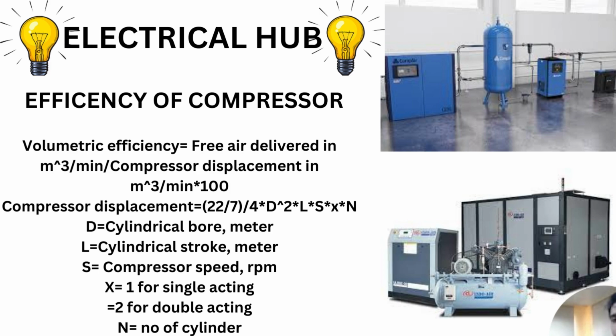Volumetric efficiency is measured as free air delivered in meter cube per minute divided by the compressor displacement in meter cube per minute.